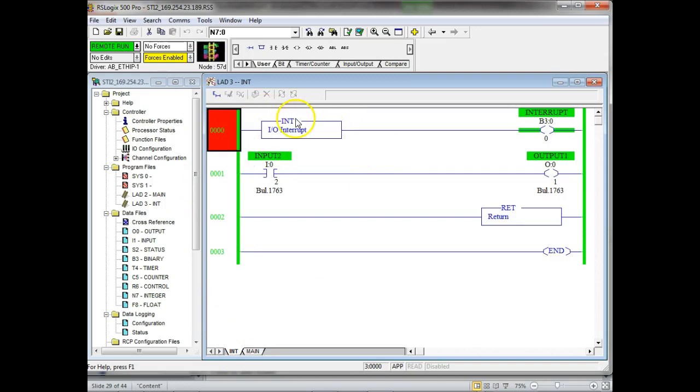So we started it. There's that INT instruction. What does that identify it as? It identifies this as an interrupt service routine instead of a subroutine. That guy right there is optional, guys, but you need to put it up there so that when you go back through your service, you can identify which ones are subroutines and which ones are interrupt service routines, right? So I've got this hooked up to switch 2.